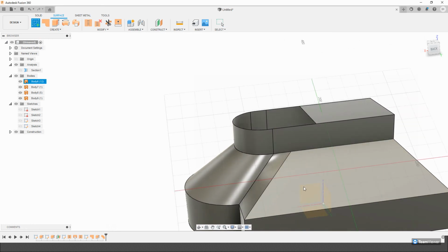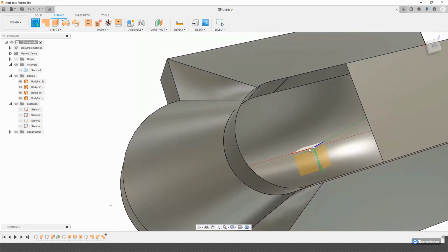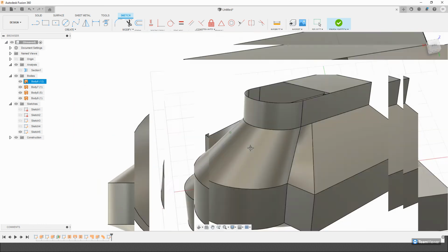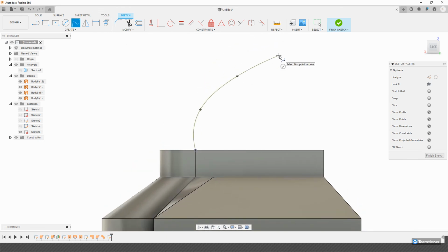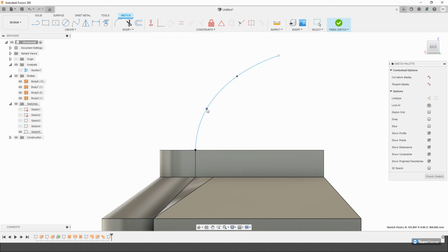I'm going to perhaps create a sketch part to do a sweep very quickly. So I'll probably say something like, let's try and project that line or that point. Remember, when working with curve shapes, the fewest lines the better, because control points can really come back to bite you later on.